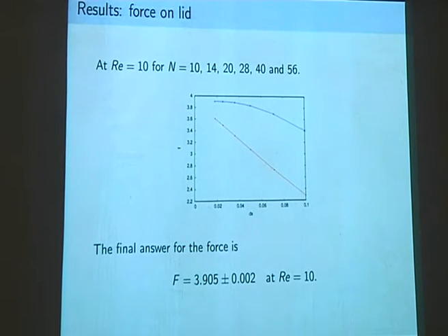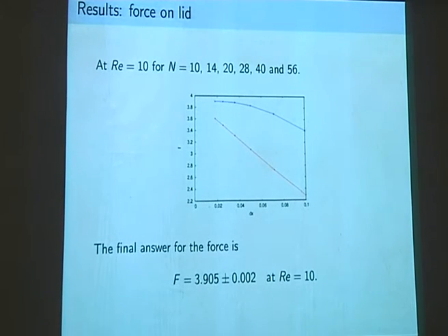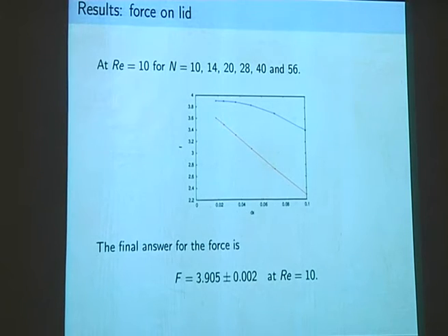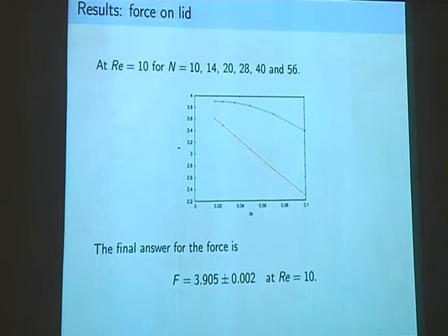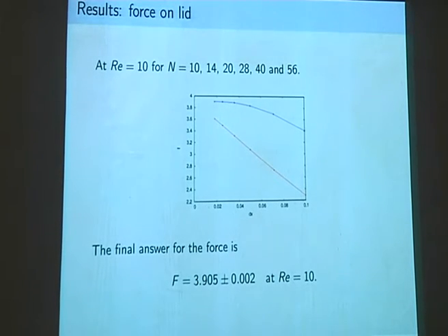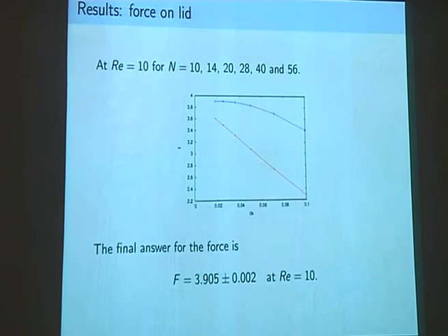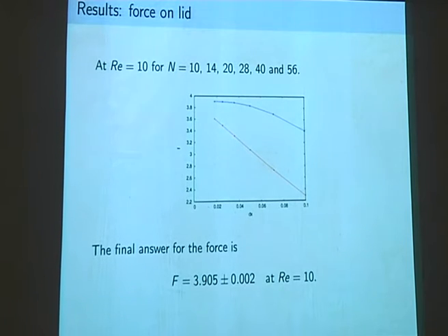And from this second order accurate one, the answer is 3.9. And from these, you can actually take these two points here and extrapolate those. So while the answer is 3.9, these grids with the first order accurate answer are sitting around about 3. That's a very big error, 30% error. Although there's a 30% error here, the linear extrapolation of these is 3.9.